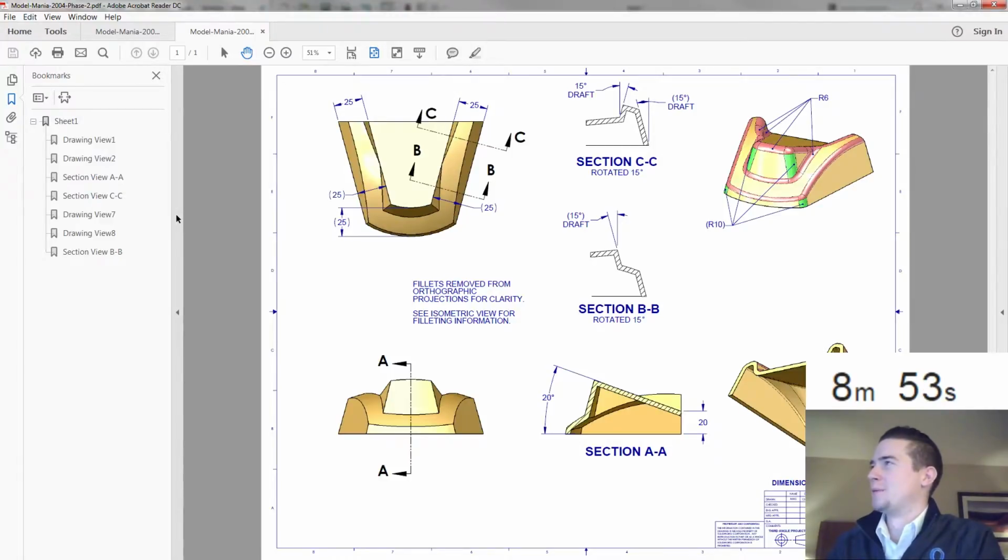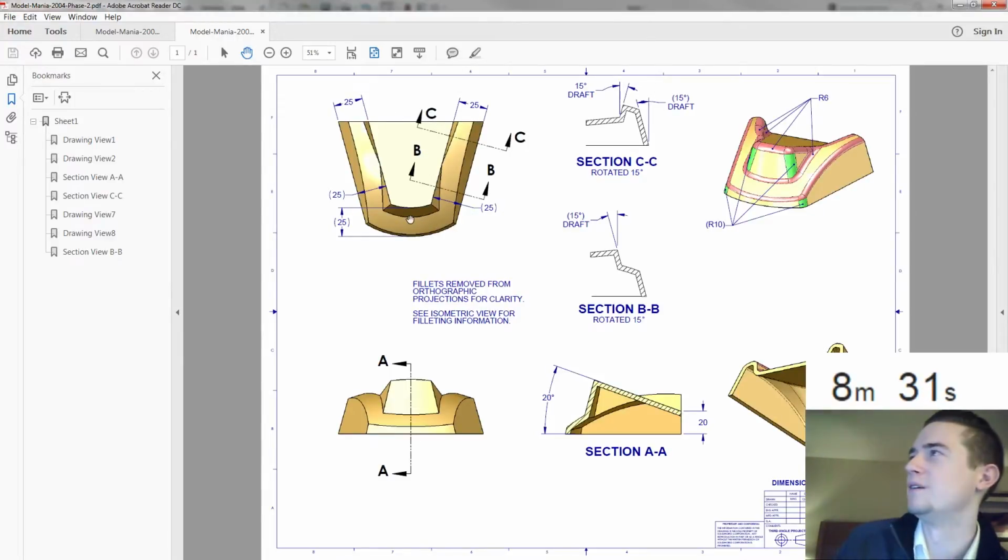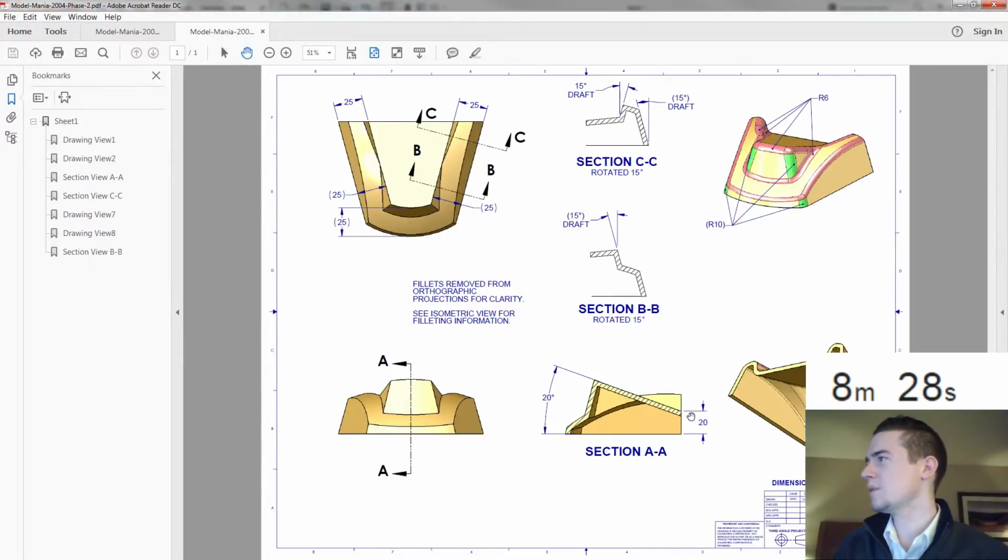So let's kind of roll back before those fillets. We can maybe do a replace face with just that angled face in the back. So we'll just kind of go back into surfacing and replace face. What is the dimension there? So we just have this surface of 20. I wonder... Everything else seems to be the same. So we still have this 25, 25, 25. That's fine. Got this 20 coming from the back, so 15 degrees draft still going on. That goes on the inside.